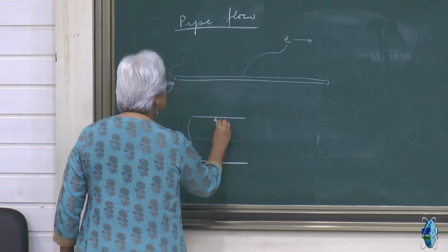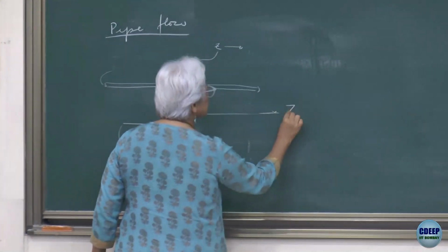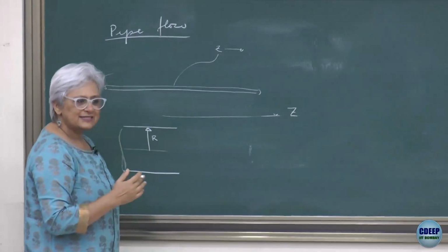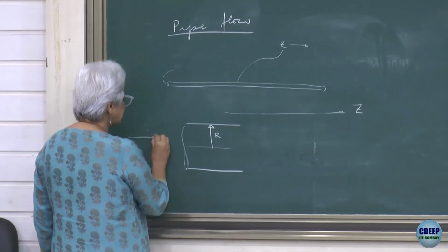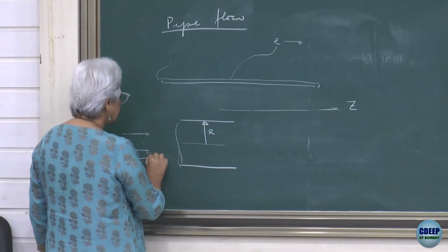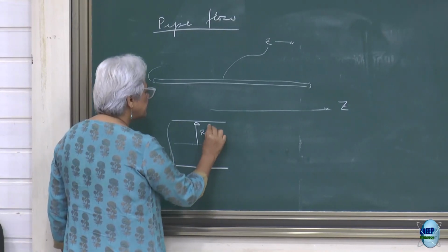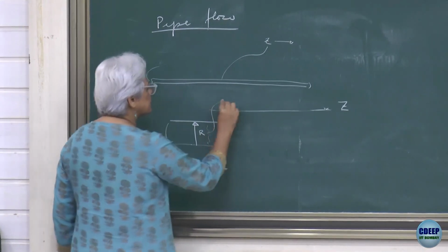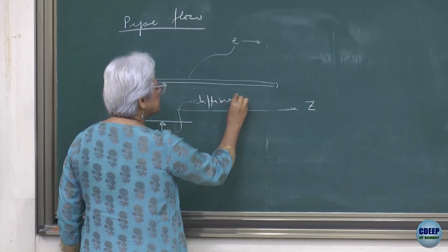what we are looking at is a pipe with radius R, and this dimension is going to be long, and as the aerosol laden flow is coming in, you are going to have particles starting to diffuse in the radial direction. So, you have diffusion in the radial direction.